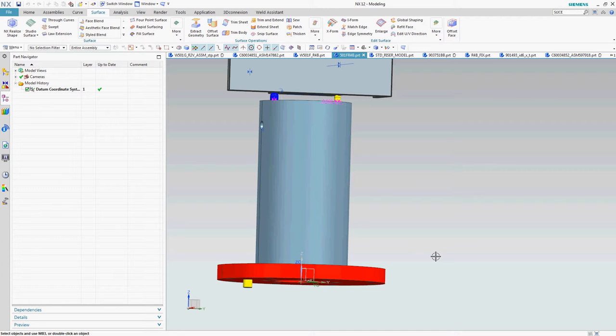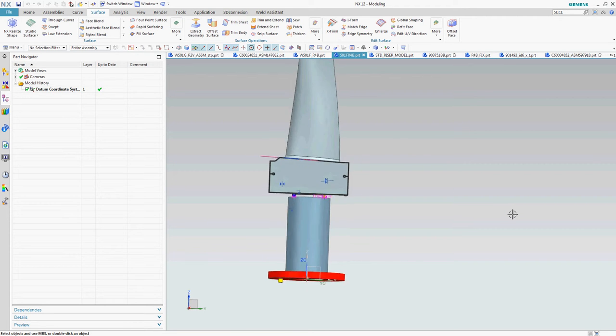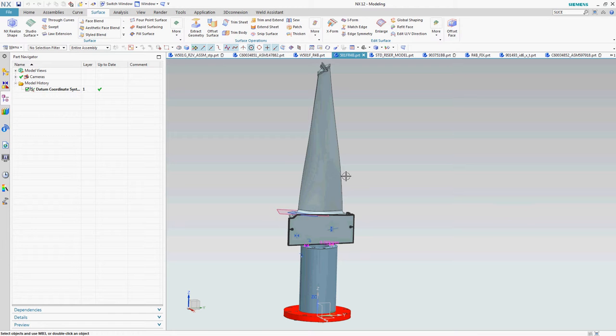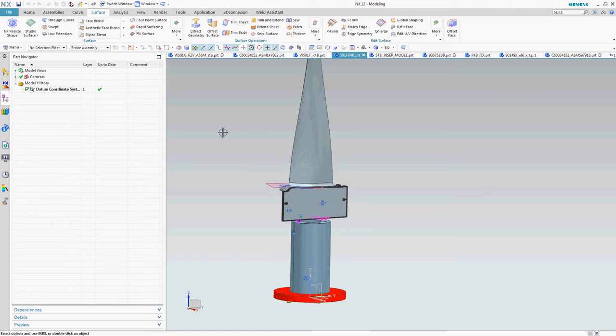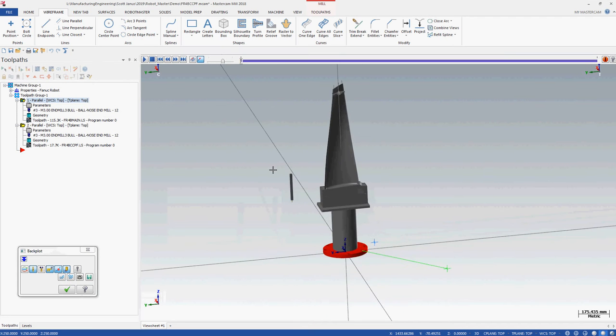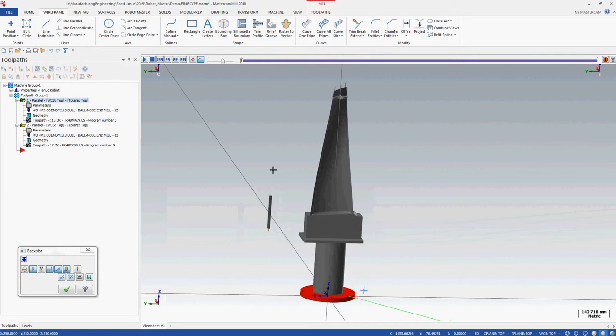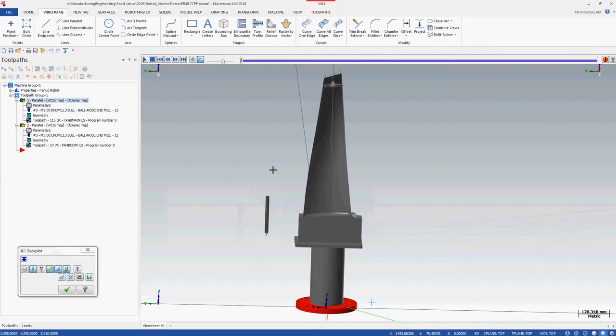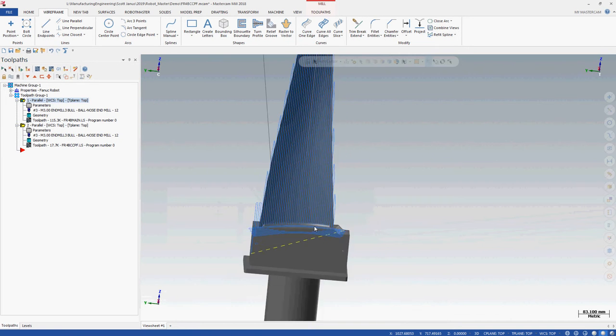First, I'll show you the basic configuration. The main thing you want is your datum CCs to be at 0, wherever 0 is going to be on your robot and how you're structuring your robot assembly and fixture. In this case, it'll be on top of the rotary table. So 0 will be here. This will sit on top of the rotary table, and that's where we'll rotate about.